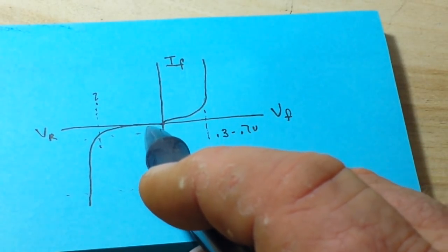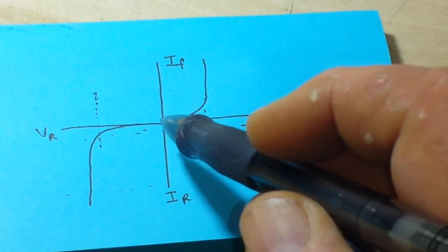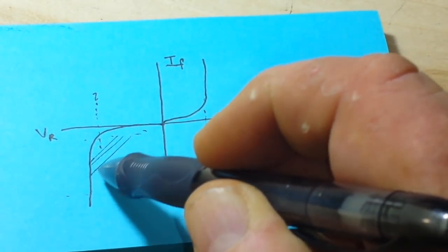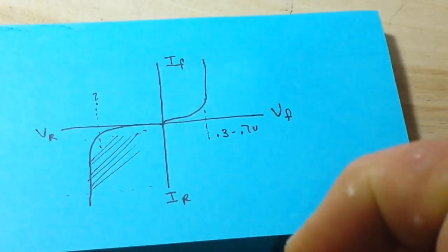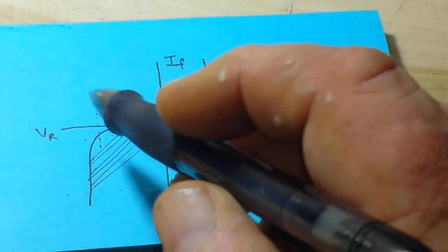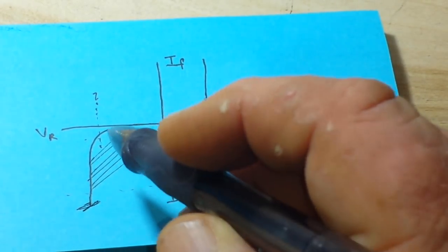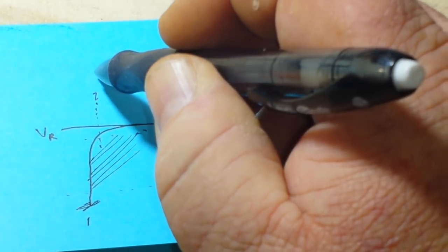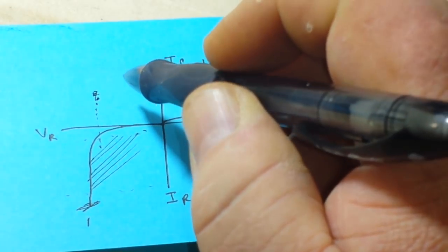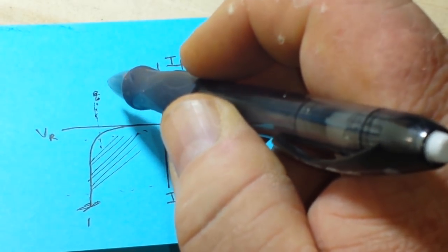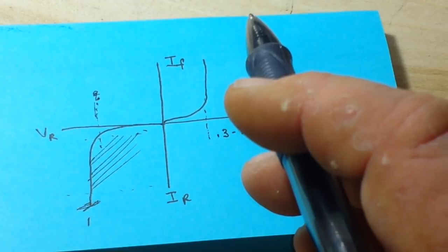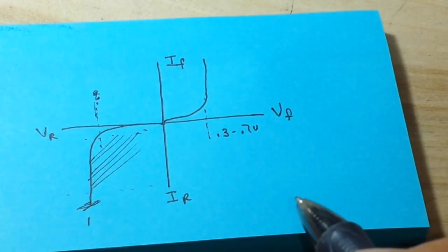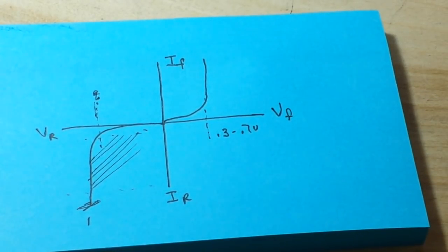But if we reverse bias our Zener diode, well, we have this whole new area here that we can play with. And now we have a controllable voltage here, because that voltage, whatever it may be, will not pass this point. And that's why the Zener can be used as a clamp or as a crude voltage regulator. So we'll take a look at that in a future video, but there's something else I want to talk about today.